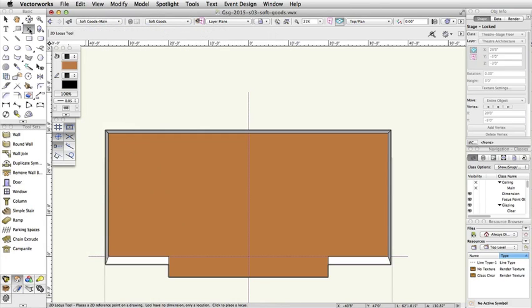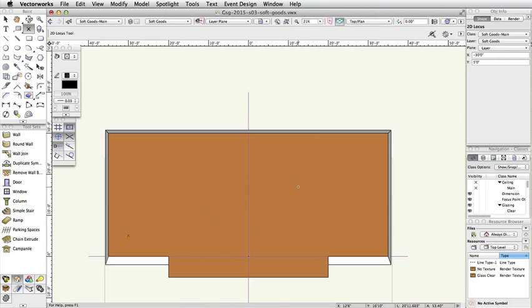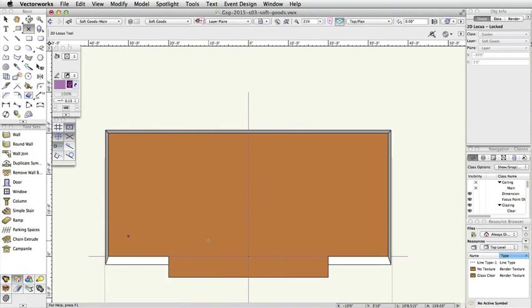Double-click the 2D locus point tool in the basic palette. Set X to -30 feet, Y to 5 feet, and click OK. Convert the 2D locus point into a guide. Modify, Guides, Make Guide. We can now use this locus point to start our first border.